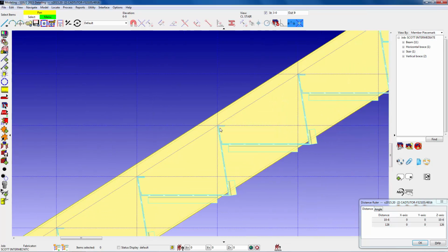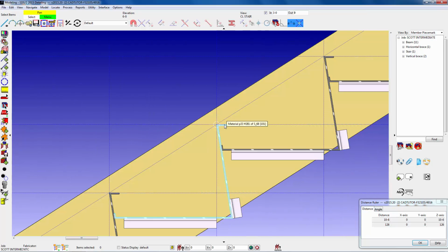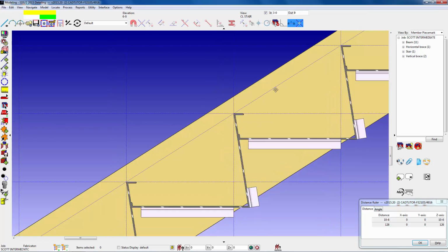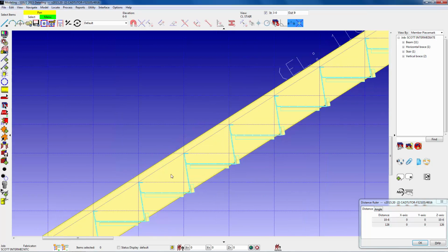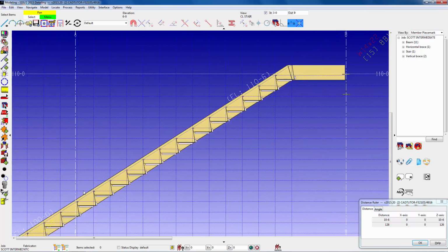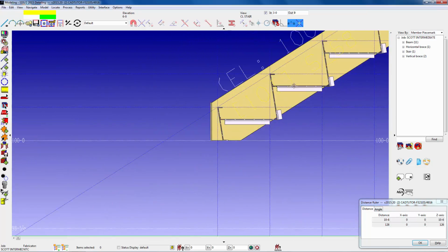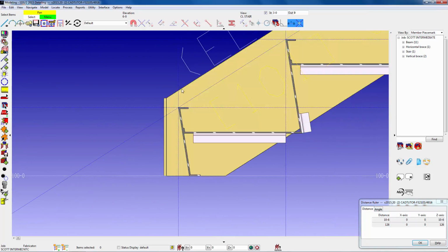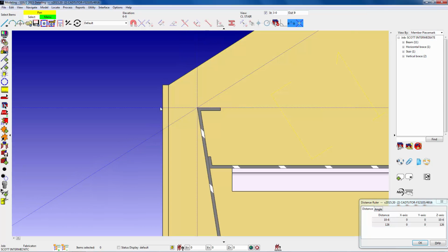And stair schedule number 1 is a pan stair. So you can see as I highlight this pan here, that's the pan itself. And as I zoom down to the bottom here, the dimensions we put in at the bottom, saying bolt to floor, it cuts the stringer at the floor line and at that 1 1/4 inch dimension we put out here. It added on a 1/4 inch cap plate.